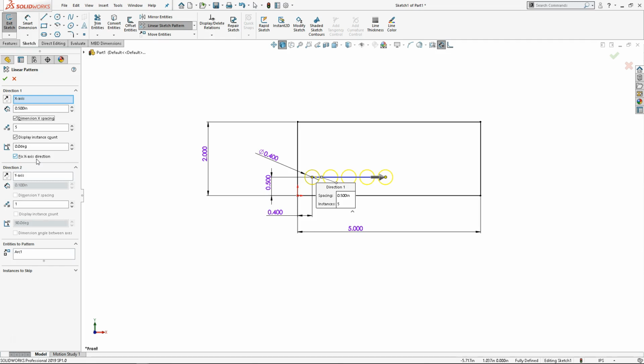When I do that, I do not get the direction arrow. Okay, so once you hit Tab, and I may have overlooked it, my index finger jumps up there and hits Tab and shows the preview. Once you have the five circles, then it's showing you the direction. Okay, and then for the X spacing, and then the X direction axis, that's going to apply a horizontal. That was not available previous to 2018 that I remember.